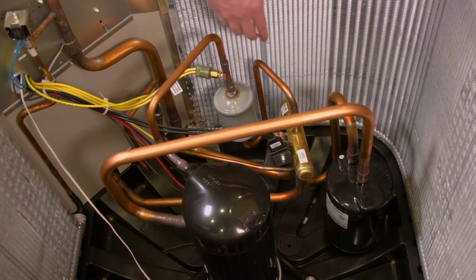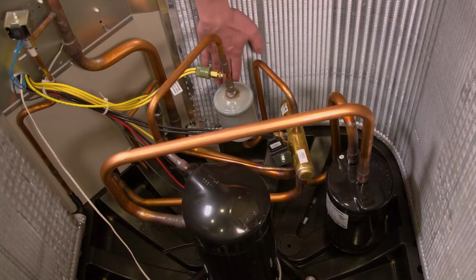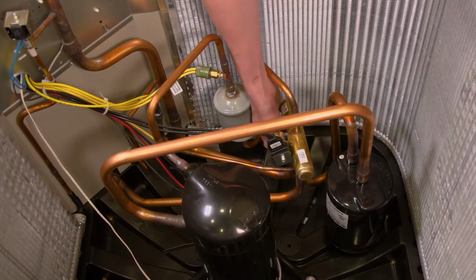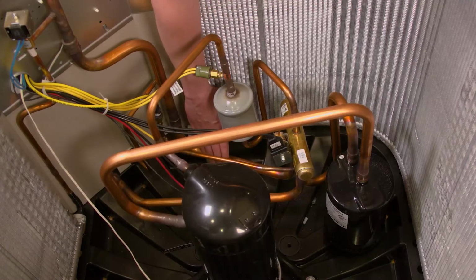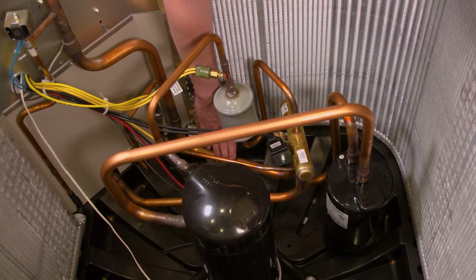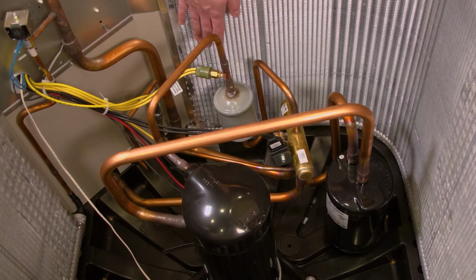And then you'll have another line coming off the other side of the valve, which essentially goes to your outdoor coil. So essentially, the easiest way to look at this is that you have one line that goes to the indoor coil, and then you have another line that goes to the outdoor coil. You will also have your common suction port hookup to read suction pressure in heat pump mode.